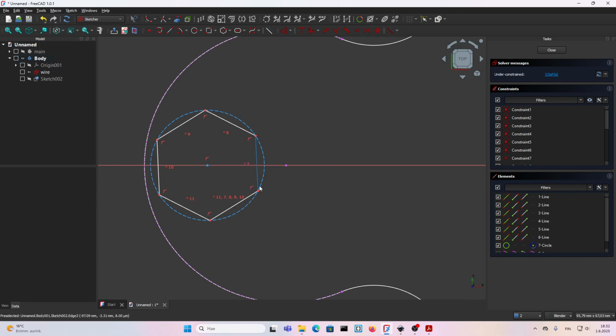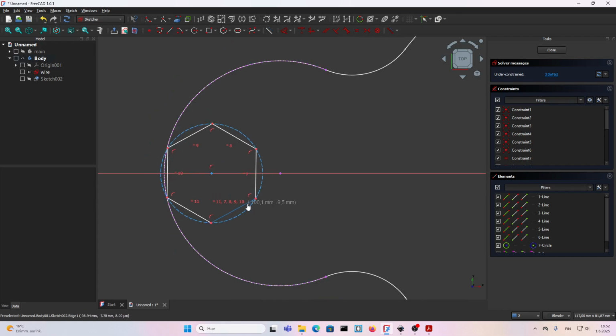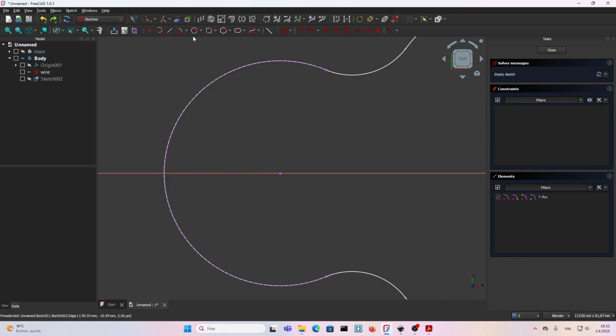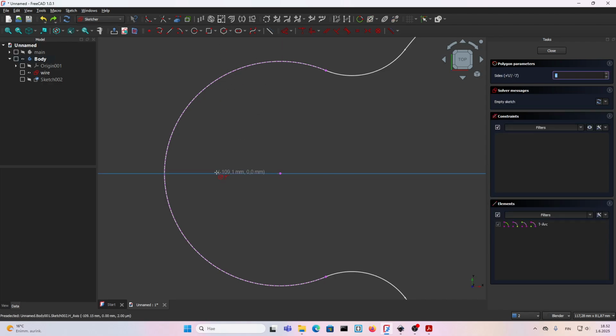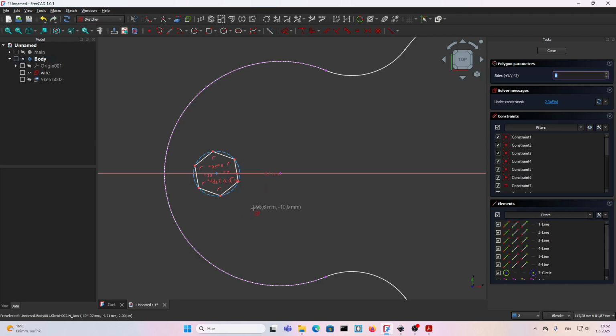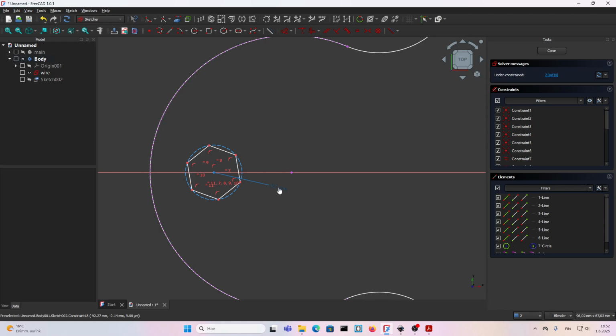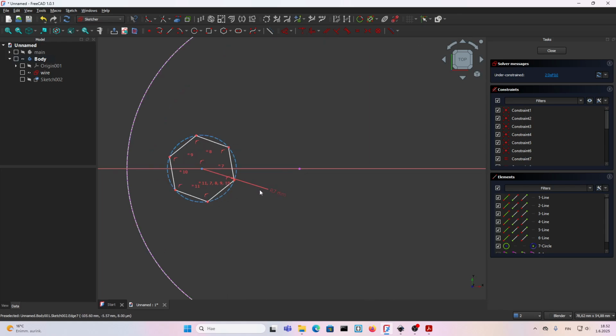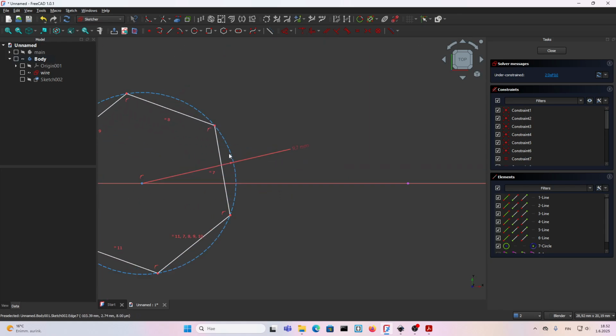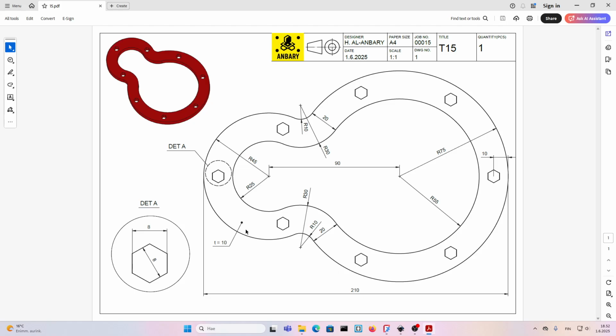Now, if you take a look at this, the dimension didn't come. I will delete this. Just a moment. Click on here, here, and I will make the 7 and okay, like this. The radius is 7 now. This radius 7 doesn't help me at all because the dimension that I need is this one. I need this from here to here to be 8 millimeters and 8 millimeters.